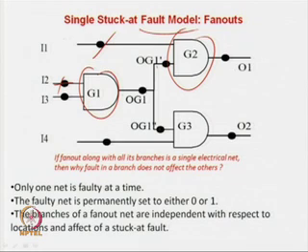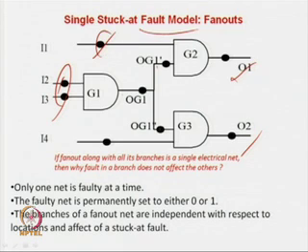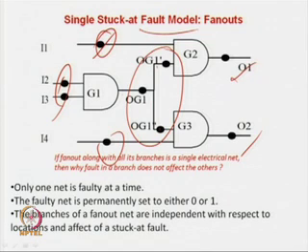So, the full circuit we are breaking down into individual nets. This is one net, this is one net, these are the two nets, and these we will see are fan out, which has to be handled separately. So, each of the nets you individually consider, and you have to apply a test pattern which will verify that none of the gates have a stuck at 0 or stuck at 1 fault.